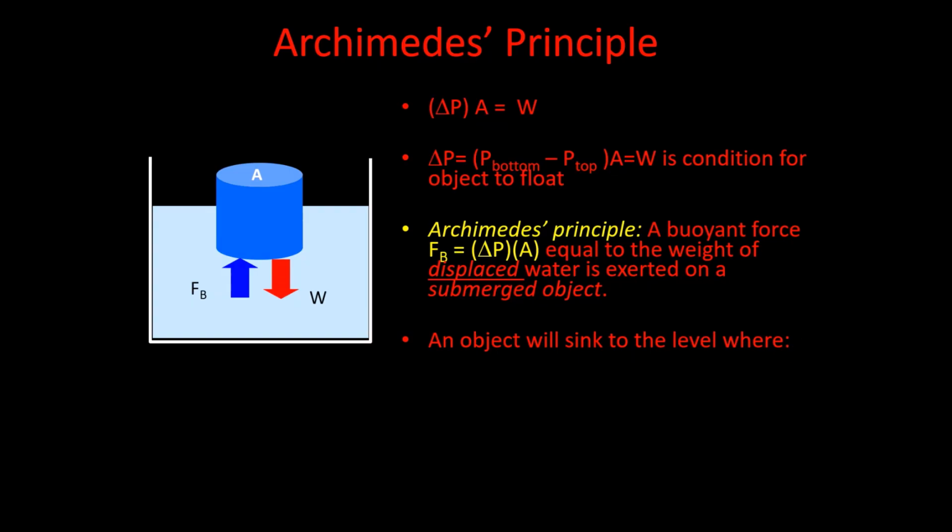When you place an object into a fluid, quite often it won't either sink or just sit perfectly on the surface. The object will usually sink slightly to some level and then stabilize with the water either halfway or some fraction up the object. So an object will sink to a level where the buoyant force always equals its weight. So Fb will equal mg.